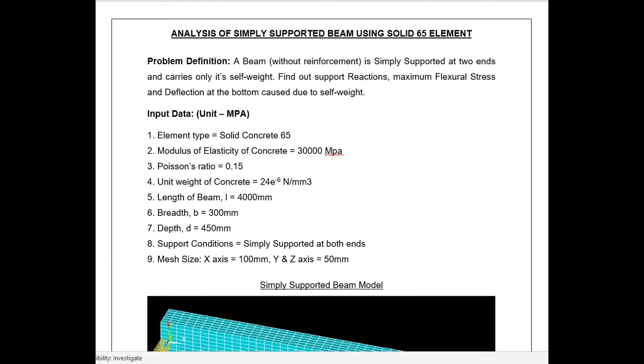Hello viewers, my today's video is based on the analysis of the simply supported beam using element SOLID65. In this problem we consider a beam without reinforcement which is simply supported at two ends and carries only its self weight. The intent of this example is to find out reaction, maximum flexural stress and deflection at the bottom of the beam caused due to only self weight.